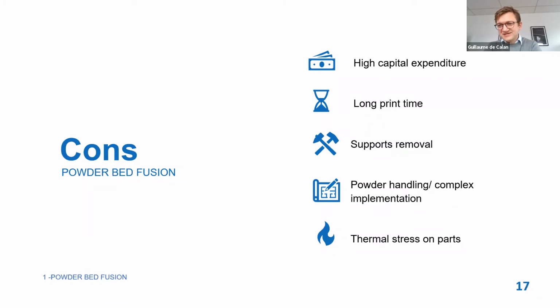And on the cons also, well, you are handling metal powders, which may seem obvious, but not all technologies need to handle metal powders. And metal powders are a serious hazard, both in terms of health, also in terms of danger of explosion. Metal powders are usually flammable and explosive, which means if you want to do this in a safe way, you actually need quite a complex environment. You, of course, need protective gas, but you also need your workers to be in specific outfits with protective gear. Well, this makes it really a heavy investment, both in capital and in environment.